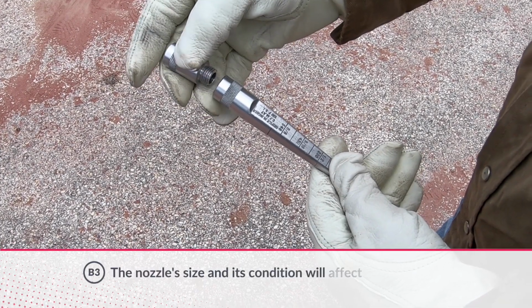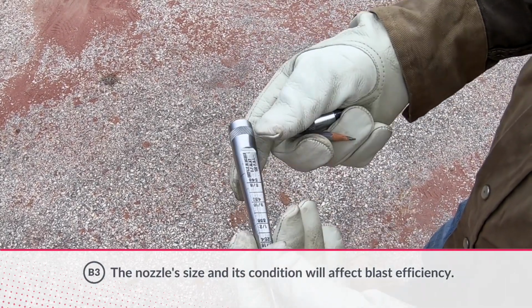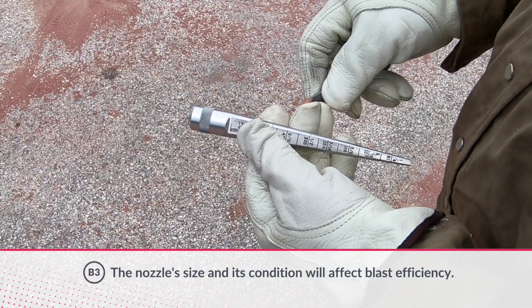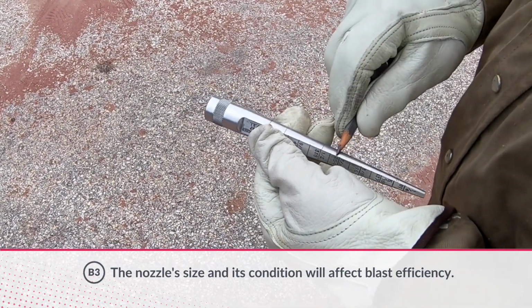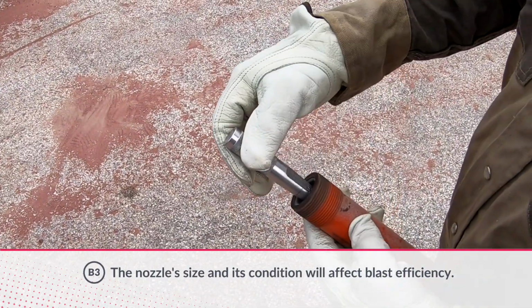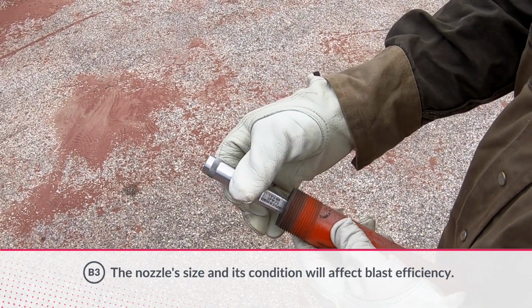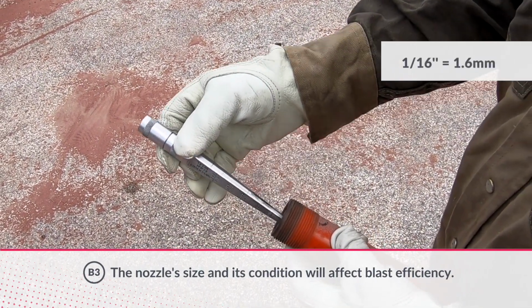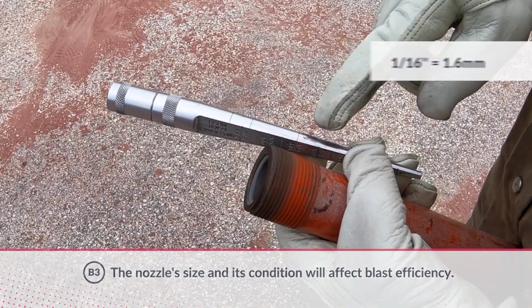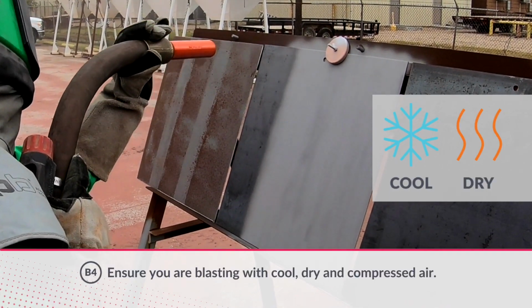Nozzle sizing should be dependent on the project specification and air availability. Its size and condition will affect blast efficiency. A small increase in nozzle size will result in a large increase in air and abrasive consumption. Check for nozzle wear with a nozzle sizing gauge prior to each shift. Replace the nozzle when it is worn to 1/16 of an inch from its original size, which is the equivalent of 1 nozzle size. Cool, dry compressed air blasts up to 15% faster.